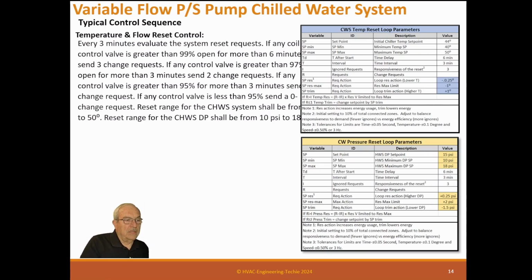10 psi also needs to be established during test and balance, but that'll be a procedure that's not normal. So normally, for set to 15 psi, you would test everything at the maximum flow for design flow. But at the minimum, probably go down and open only 10% or so and close the rest and see what pressure you need to fulfill that and make that the minimum one, and then go from there. That's kind of variable, whatever you decide to do.